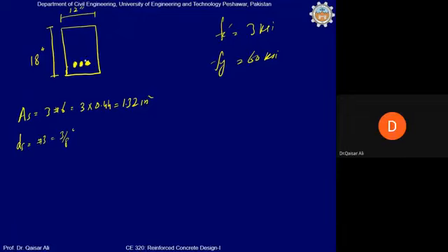Okay sir. How will we calculate this D? We studied it in the last class. Effective depth. How to calculate this effective depth? H minus 1.5 minus diameter of the stirrup and longitudinal bar divided by 2. Roughly you can take H minus 2.5 for design, but since this is a given reinforced concrete section, everything is known to you. Diameter of longitudinal bar, diameter of stirrup is known to you. So for this you can calculate the actual value of effective depth, and that is very simple.